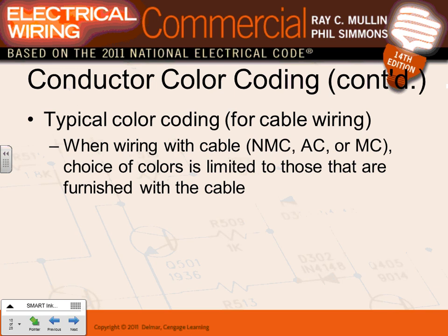When you're using cables, we looked at the color codes. They typically use the same color coding that we use in conduit for the most part. But if you have conduit, you can pull any color code that you want. If you're using cable, you're limited to what the manufacturers of the cable use.